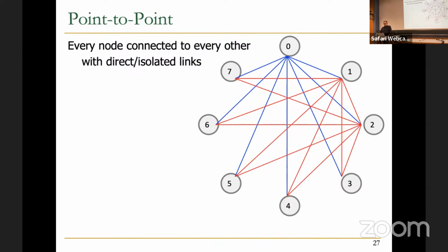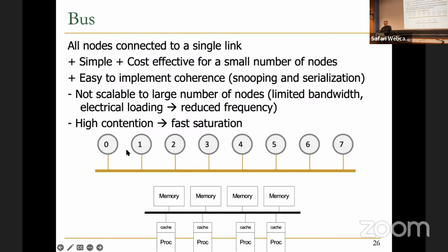Yeah. In a bus, there is a module somewhere that does arbitration. So every node should send a request to that arbitration. And then we have these arbitration cycles where the arbiter arbitrates across the active requests. There can be a lot of different policies. It can be round robin or anything else.